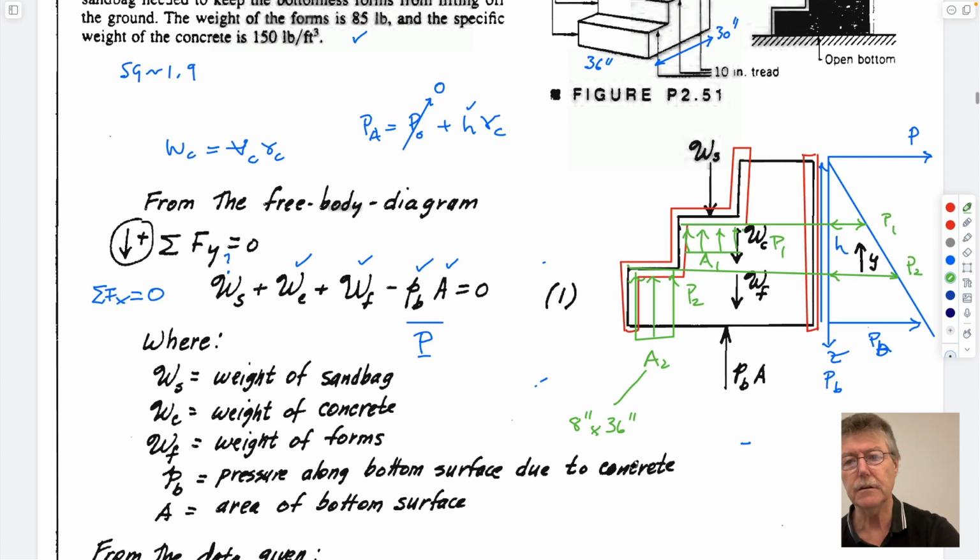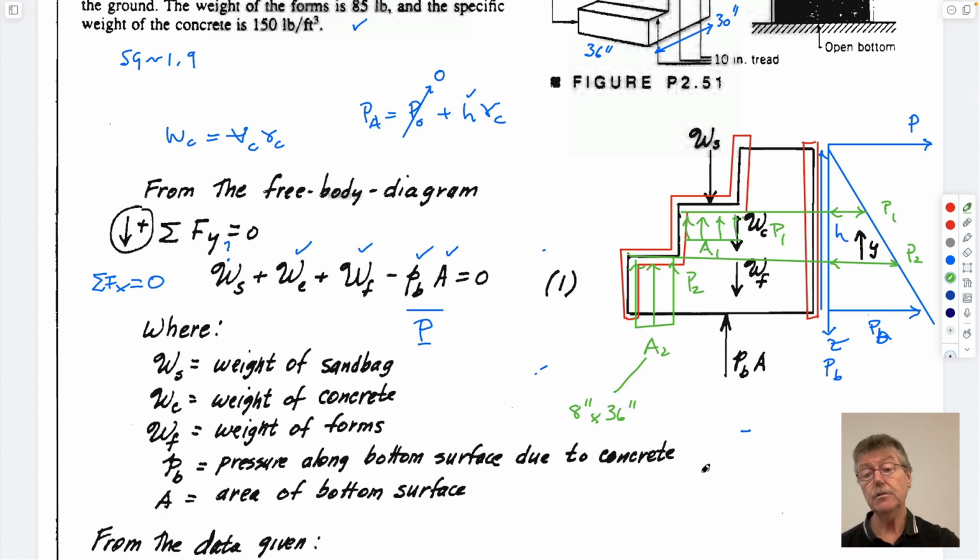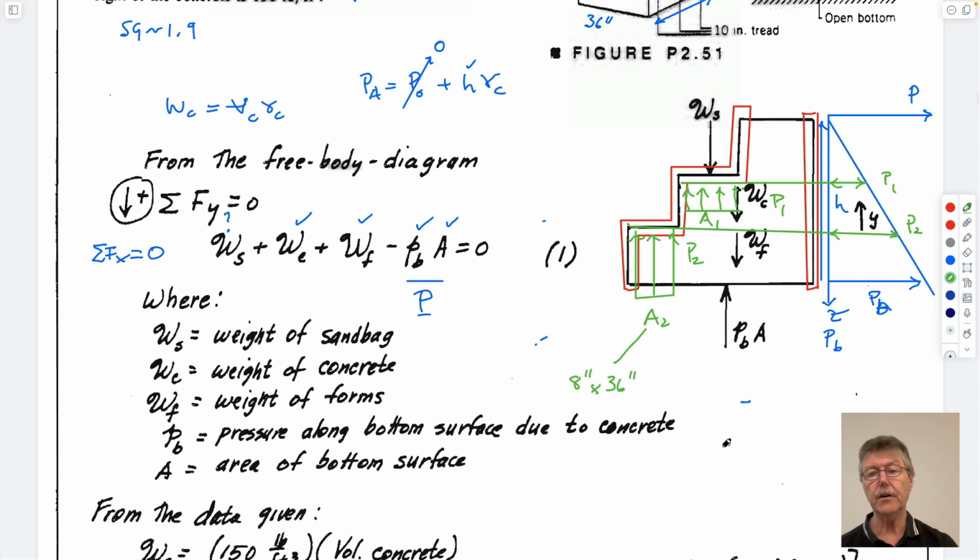Horrible units. Who invented those damn units? And so we could do a different free body diagram. The free body diagram would be P2 A2, which is a force acting upwards, plus, just keeping the same sign. Actually, this is in the right orientation, right? Positive upwards. This would be P1 A1 minus equals 0.